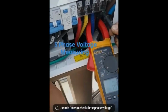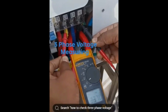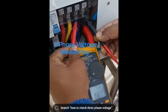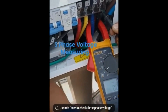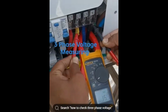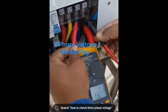Make sure your meter leads are in, consider gloves. Now we will place the black probe on neutral, and then we'll go to L1. We will get about 230 volts. Then we'll keep the black probe on neutral and we'll move to L2. We will get the same voltage, and then we'll move the red probe to L3, still keeping the black probe on neutral. Notice that the voltage will be equal between L1 and neutral, L2 and neutral, and L3 and neutral. This is measuring of single phase.